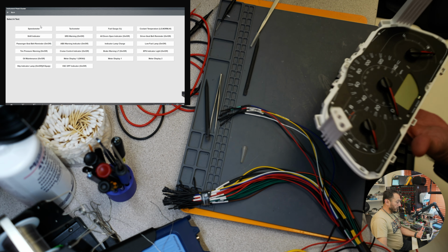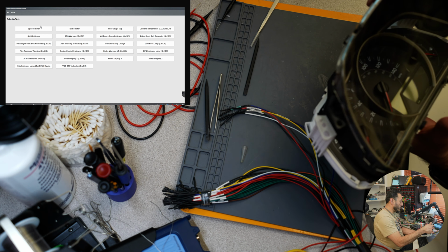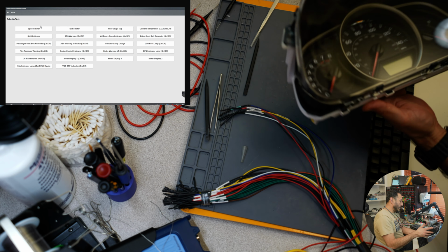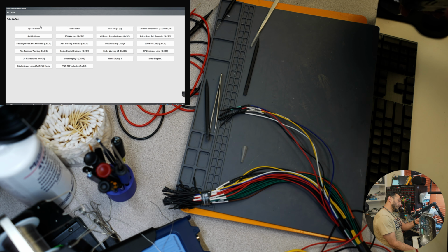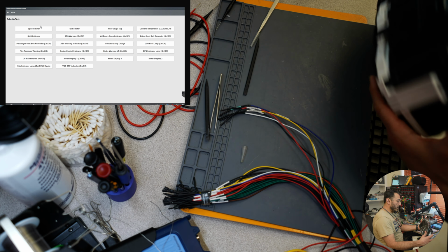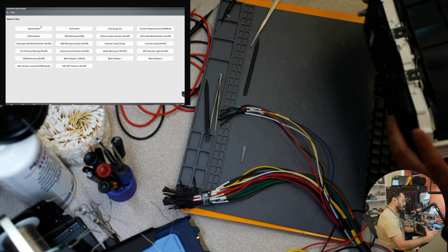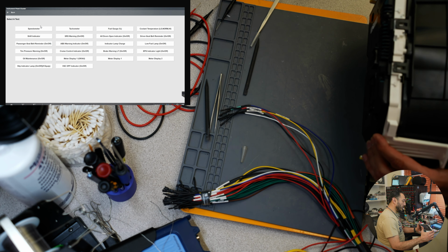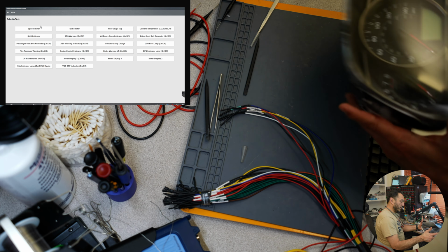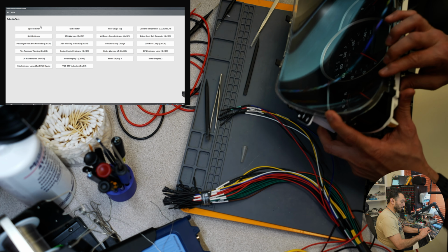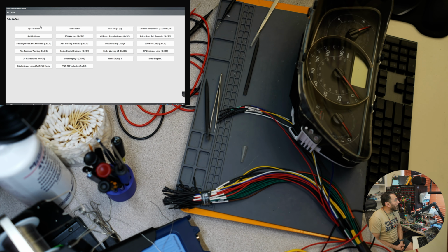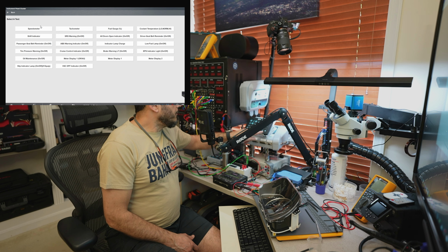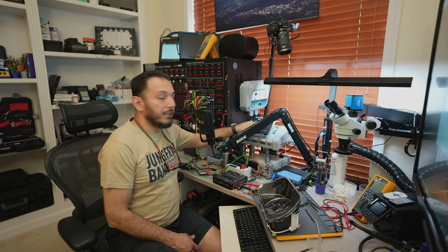And then put the bezel on, which you guys just better be careful with. It has its guide, so it will fit in these 3 points in here. 2 clips on each side on the bottom, and then 4 clips, 2 on the side and 1 in the center. So as long as you see that they're in the correct spot, all you need to do is just press. And now we have a completely put together and calibrated speedometer.